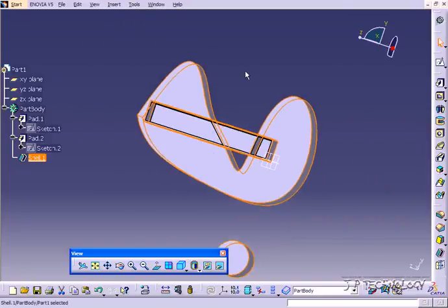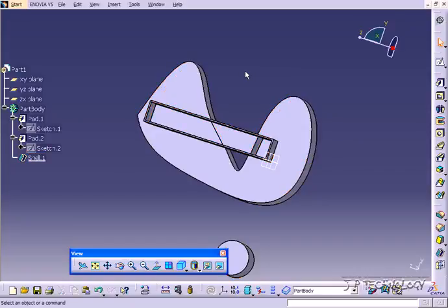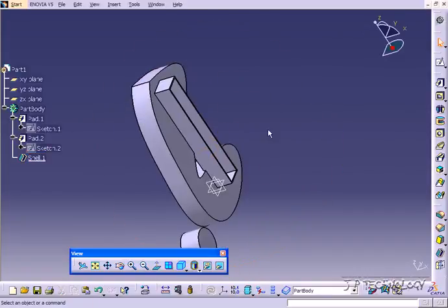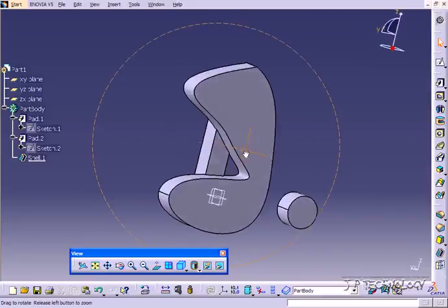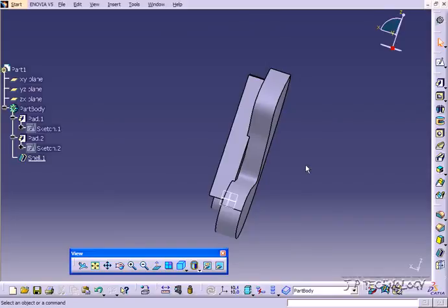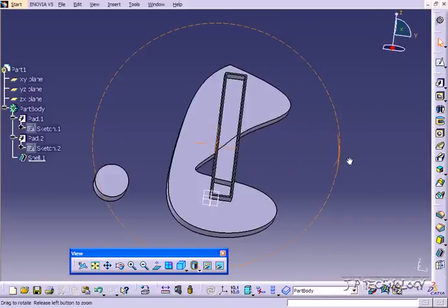So with the shell feature, you're able to make molded parts. If you have a part, you're able to shell and make the negative for it. I made a unique profile and design here, not something that you would want to go back and slowly create a minimum thickness for and shell out. Using the shell feature allows you to create that negative quickly and easily.